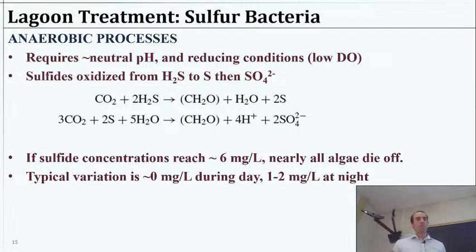So that clearly can be a problem then if we have an anaerobic process that's producing a lot of that. Are we then discharging that out and making a big stink? Thankfully, in our facultative type systems, we can also get oxidation to sulfate, right? So if we take H2S to S and then to sulfate, that's going to require a lot of oxygen, but that will stabilize it to sulfate instead of just these hydrogen sulfide. Okay, so we can take a look at that.